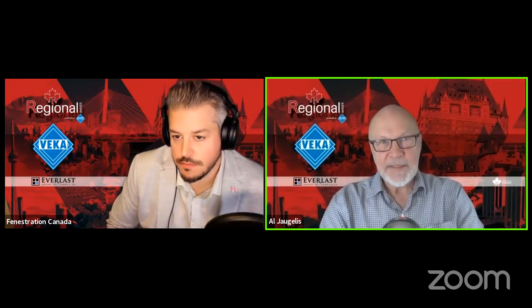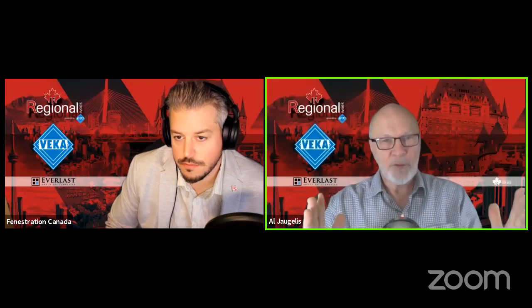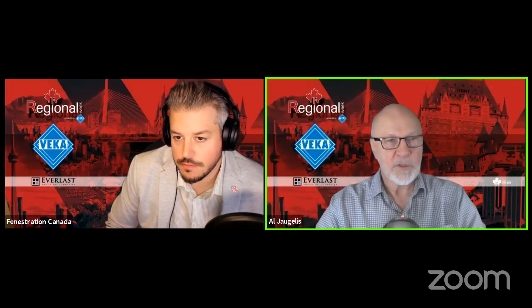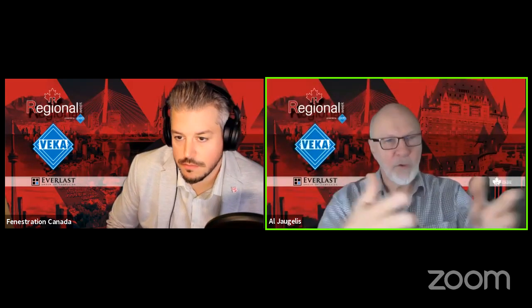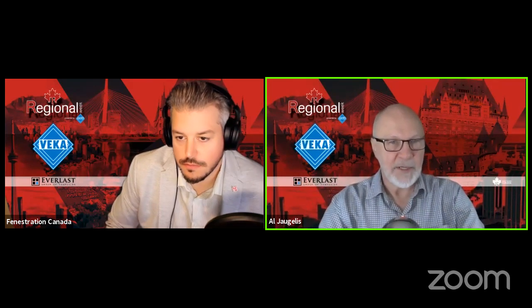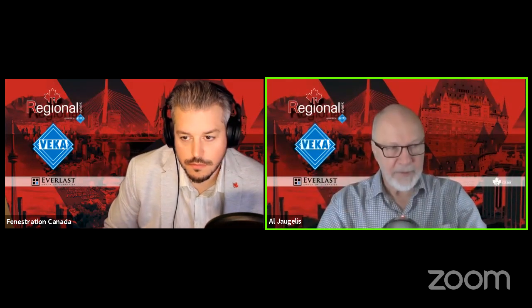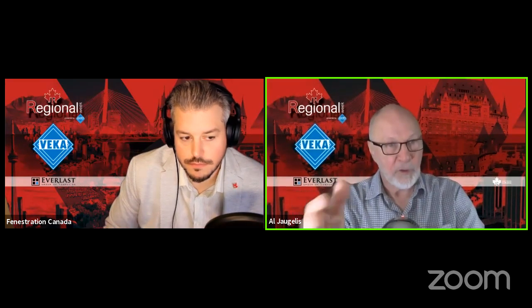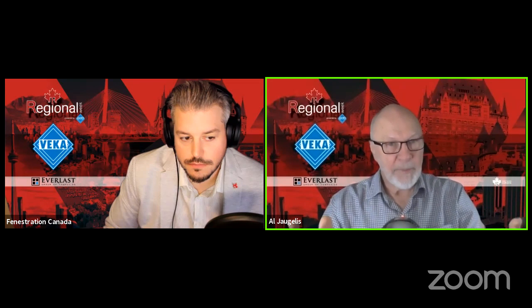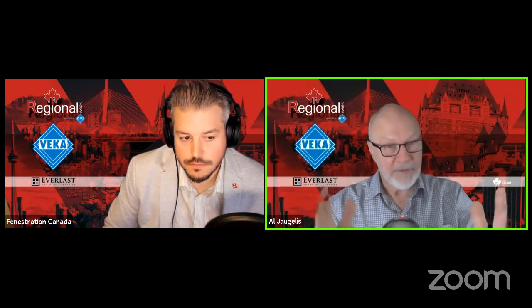I think what Ashley is asking is that some larger windows are assembled from smaller windows. For example, you may have a window that is composed of 4 smaller windows that are mulled together to make a large window. So 4 individual window frames are assembled together on site using components from the manufacturer to create a large window. So what is the water penetration resistance of that assembled window? Well, for the water penetration and the structural performance of this, NAFS calls that a combination assembly.